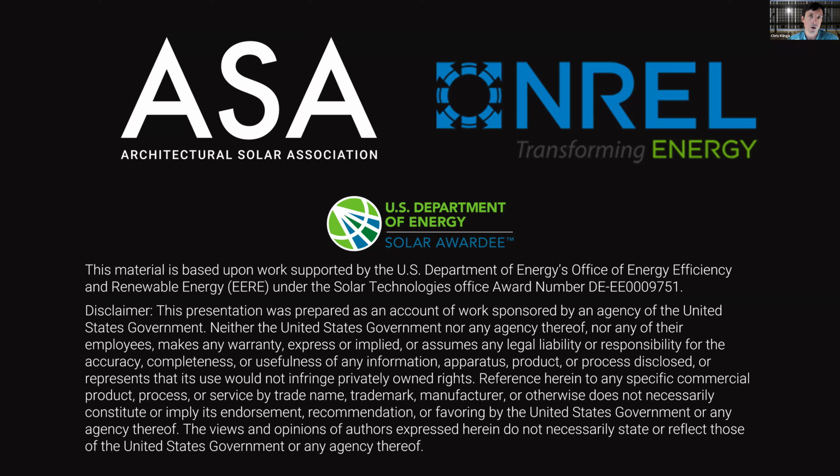In certain jurisdictions today in the US, it's not totally clear whether rapid shutdown devices are required for facade mounted applications. There are plenty of places in the code that point to those being focused on roof mounted applications or overhead applications. It's an unknown today, but I think the real research needs to be done on whether the assemblies have risk of accelerating a fire in a facade. And that's where a lot of fire testing needs to happen.